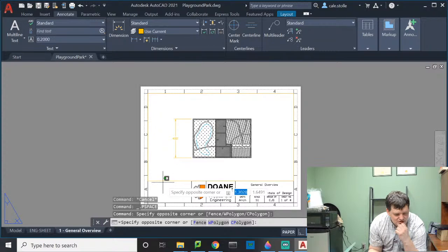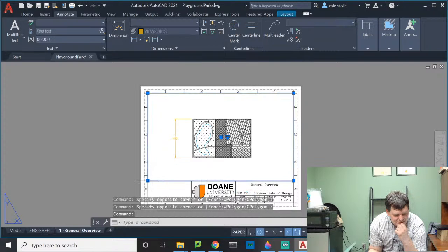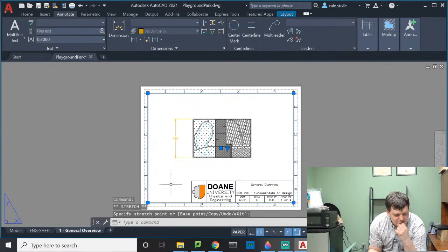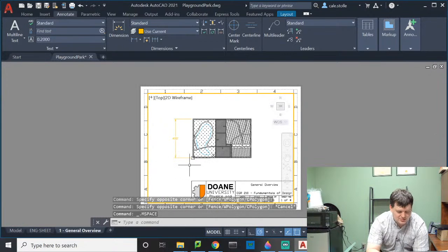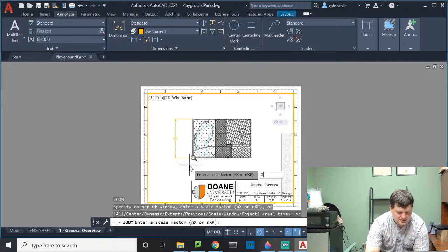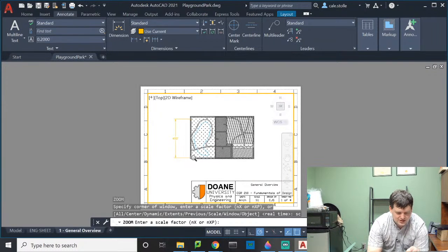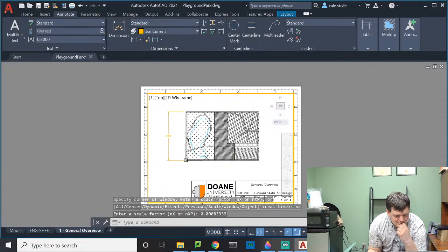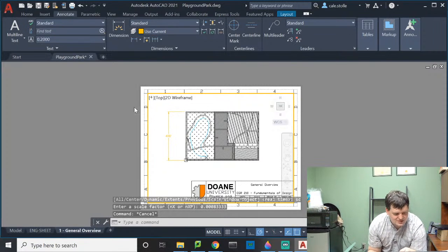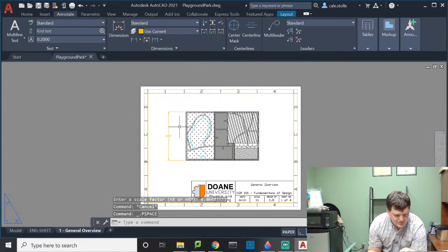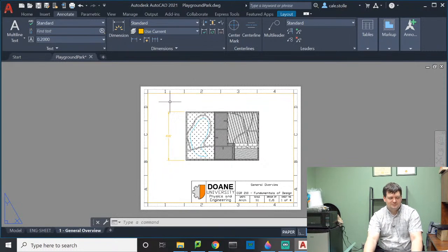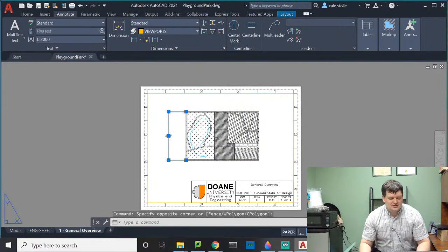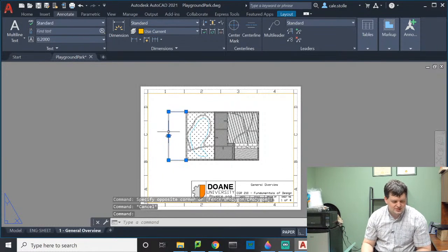Oh, maybe I need to make my viewport fill the whole screen. I think that's what it is. I'll stretch my viewport down to the bottom. Go into my model space, zoom, scale, 0.0008333. Yeah, and there, that's the appropriate size. It's dumb. It's relative to the size of this thing, so whatever. You'd have to make your viewport specific sizes and then calculate that based on how they show up, which I don't want to do, but it is what it is.